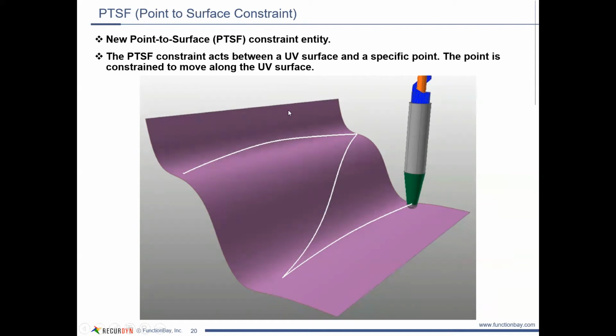The motivation for replacing the contact is that if you have situations where there's a contact going on, there's no liftoff, and you want to have as fast of a simulation as possible, then to do it with a constraint versus a contact is a very appropriate thing to do.